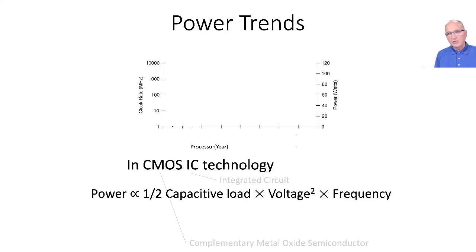But before we do that, let's review a relationship that exists between the power that's consumed in a processor and the proportions of the power. So there is something called a capacitive load that's a characteristic of the processor that will determine the power, and power will have an evolution that's linear with that. Then there is another factor that's the voltage, and the important thing to note here is that power is proportional to the square of the voltage.